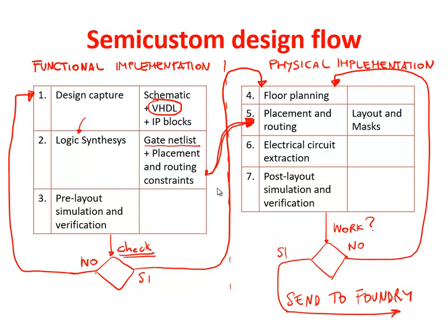So what one typically does is the post-layout simulation of only the most critical parts of the circuits, not the total circuit, because it's extremely expensive. A microprocessor can easily have 1 billion transistors, and of course, if you need to simulate electrically a circuit with 1 billion transistors, then it's not really doable. Okay. But the design flow is this one.